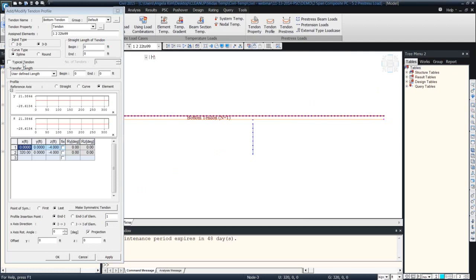And another really nice feature over here is to define typical tendons. So let's say you're working on a preliminary design step, so you do not wish to model the tendon multiple times. Then there's no need to go through all the burden of defining the same one multiple times. Just define them on the same spot, or differentiate the location a little bit. You don't have to go further for the preliminary stage. You can actually use this typical tendon option.